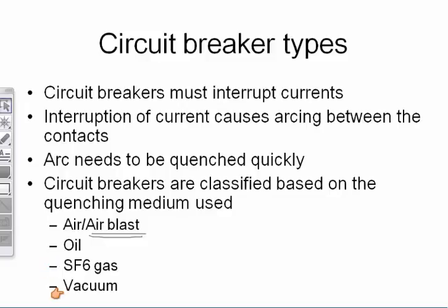Yes, good question, Nicholas. SF6 is a controlled gas. It is legal, but it is controlled under the Kyoto Protocol. That's an environmental protocol. So every organization that uses SF6 needs to document SF6 quantity on the network. Wherever you are, if you are based in Brisbane, Queensland, utilities that have SF6 switchgear need to record it and report it to the government. And you need to ensure you don't release SF6 into the atmosphere.